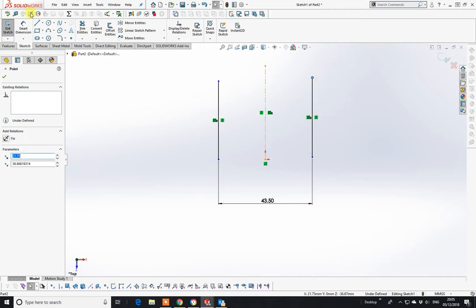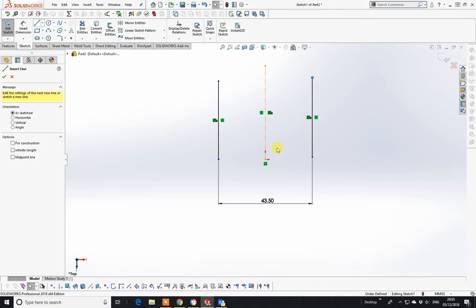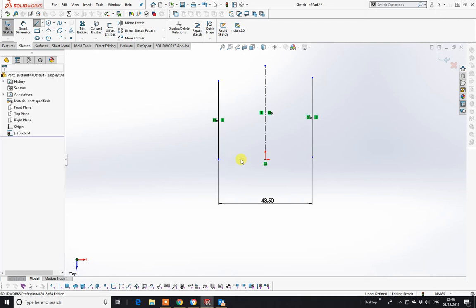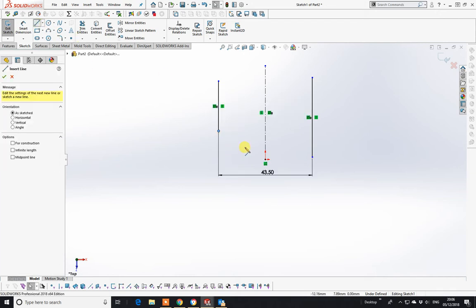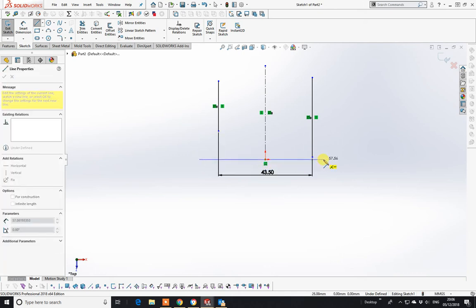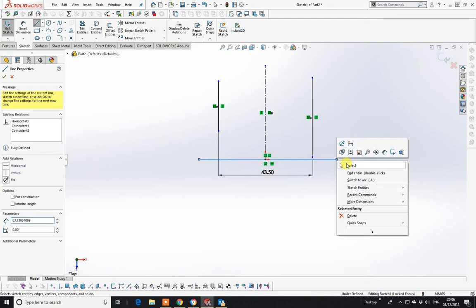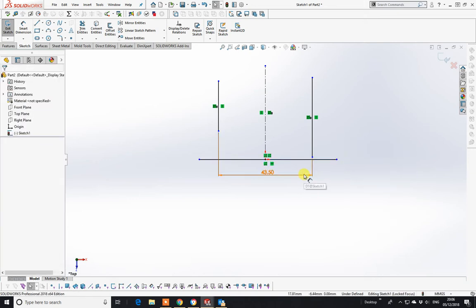Right, just to secure this at the bottom, I'm going to take my line tool again, hover over there without pressing any keys. See the dotted line as I drag it away on that one. It's actually jumped to the other one, so just press escape again, just move that one out of the way slightly. Go back to my line tool, onto there, click away, and see, I know that that line is consistent with that point that we hovered over. And see it's turned black.